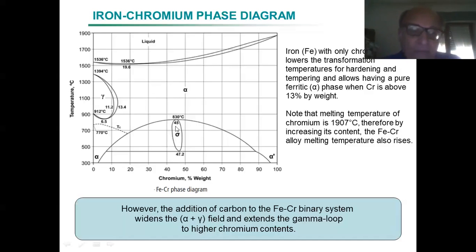You're working your alloy, and you may not need to get as far as 45%, because we are making an assumption which is not true: that if you have, for example, 18% of chromium, which is a typical situation in steel, we have 18% throughout the whole of our alloy.